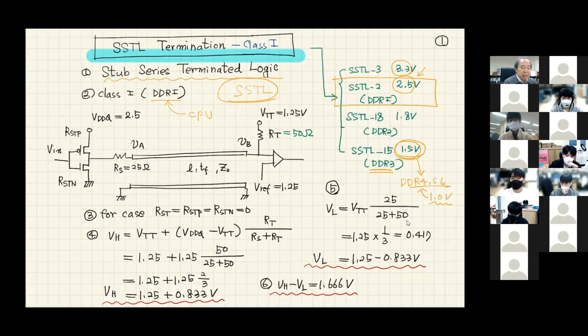One of the reasons that we are reducing this voltage level from 3.3 volts to 1 volt is reducing the power consumption, and especially I/O power consumption, because we are communicating more between DRAM and CPU and GPU in AI computers, and we are spending more and more power in the I/O. Traditionally, power consumption occurs mostly in the cores, which do all these digital calculations. But as I know, more and more power consumption is happening at the I/O circuit.